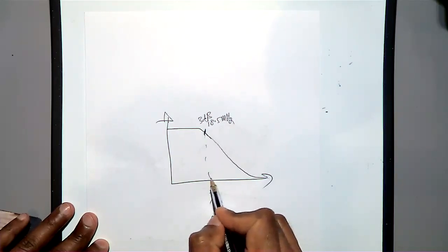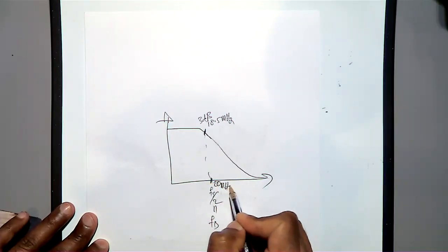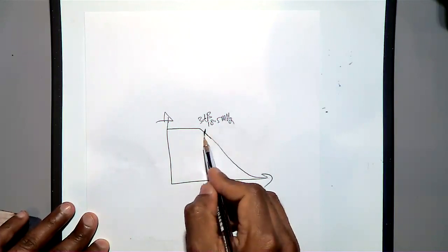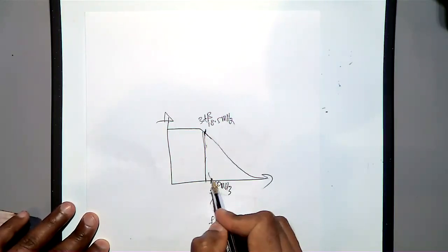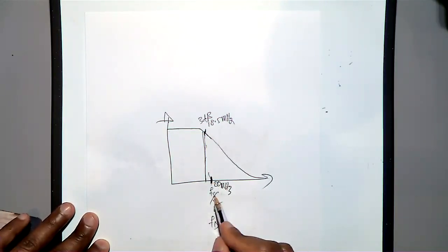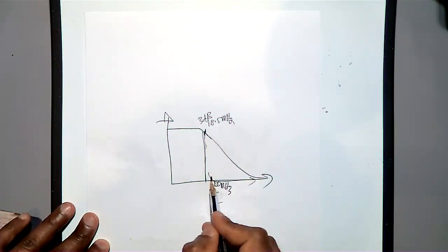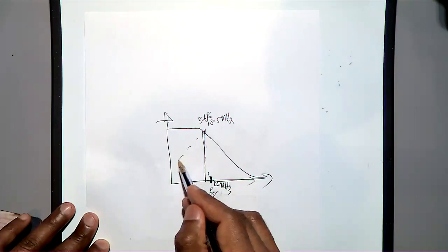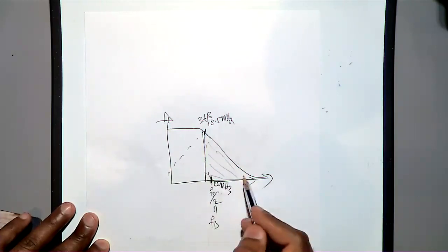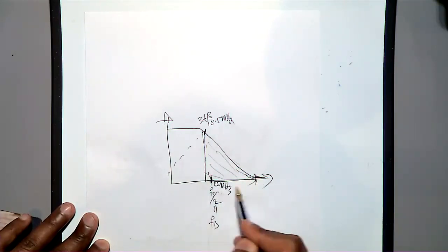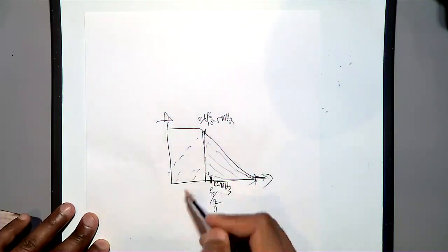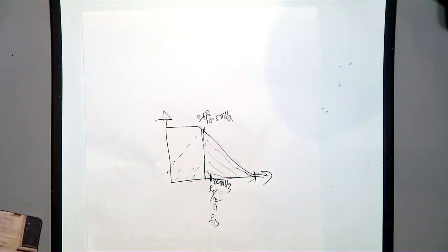So this is 20 megahertz, and your cutoff is somewhere here close to this one. So this is your Fs by 2, but still this part will be folding to this region. See, like this. Whatever the signal coming here, because your stop band may be far away, it will be folding into your DSO. So the DSO will not be a good one because you will be definitely suppressing, but that will be folding back. You know what I meant?